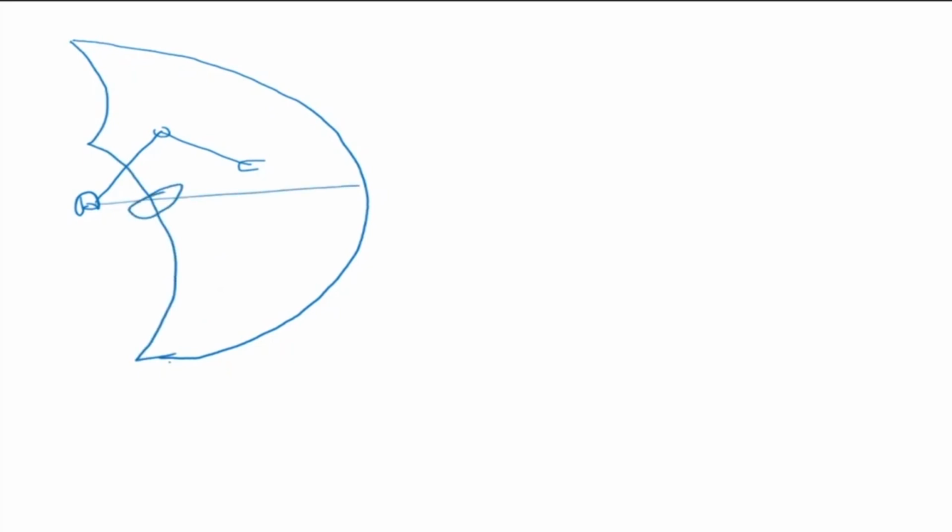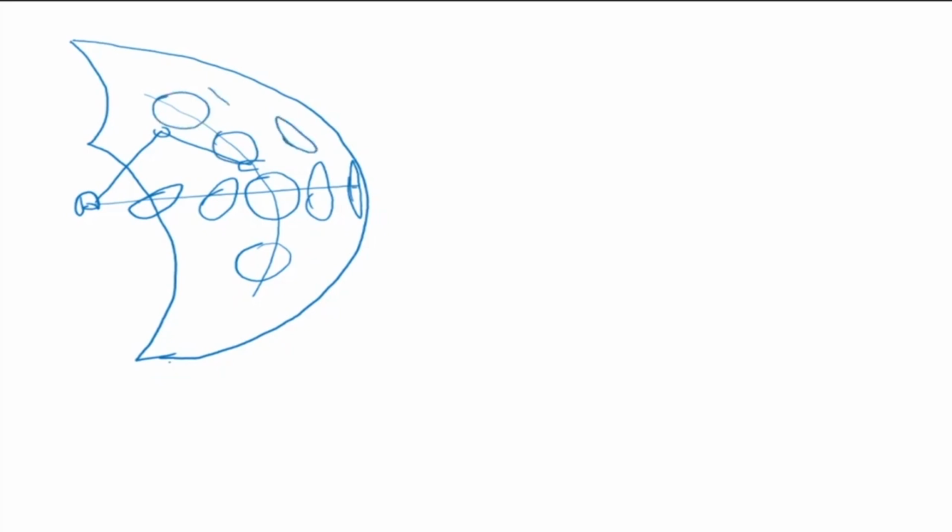Now, if you look at this two-link manipulator, along this axis the ellipsoid is something like this, and then in the center part it becomes circular, then it becomes like this, and at the point it becomes singular there. Similarly, in this region it is more or less circular, and then it becomes an ellipsoid in this direction. So this gives me directions in space in which I can move easily, and directions in which I cannot move easily.